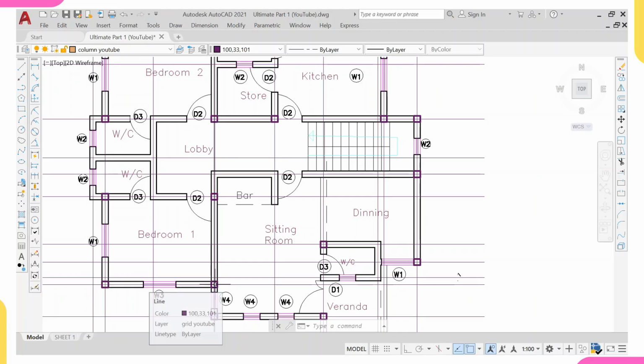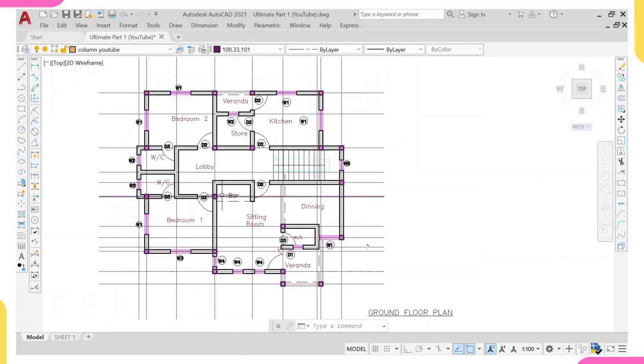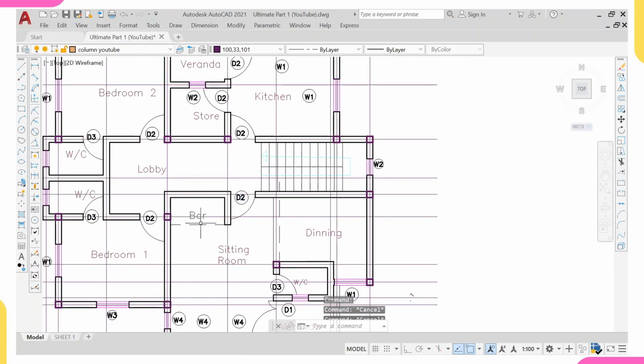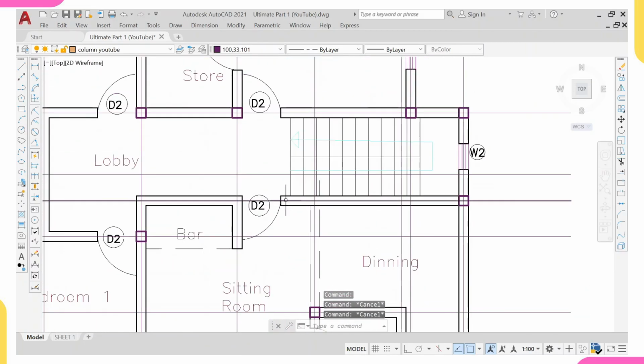because that means I'm having a bigger span. And you know that once you have a bigger span, it implies that you'll have higher moment. So I always like to limit my moment. So I will escape. Then I would also like to place a column here.